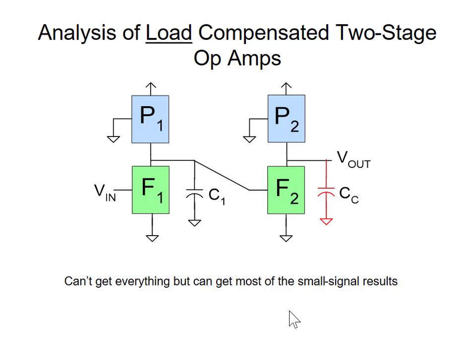While determining the poles for the capacitor marked CC, we need to consider the first stage things too, right? Okay, so what we do is we want to look at the pole on this node. So we let all low frequency poles or capacitors be short circuits. So this goes to an AC ground. If this goes to an AC ground, all we see looking in here is this output conductance and this output conductance.